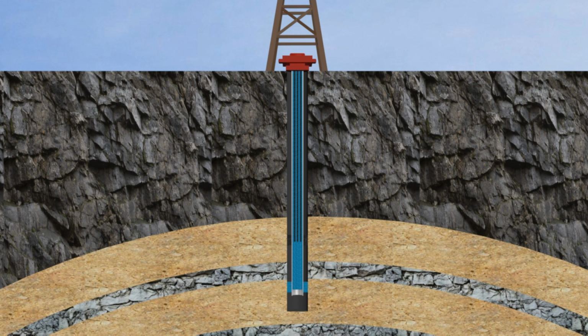In order to know, you have to be familiar with a term called wettability. Wettability is the tendency of a fluid to adhere to a solid surface in the presence of another immiscible fluid. This fluid is called the wetting phase of the rock. It represents the layer which adheres to the grains from inside the pores, while non-wetting phase exists at the center